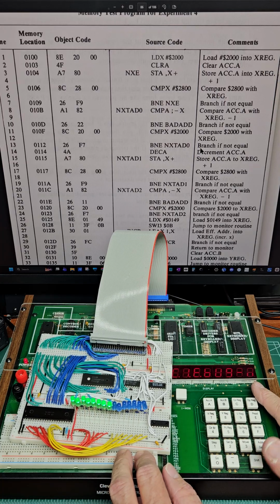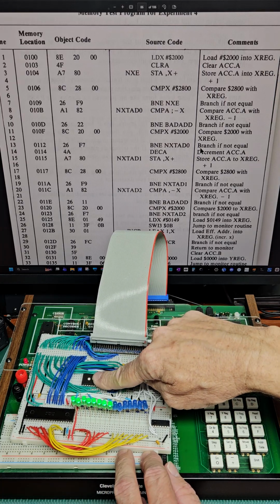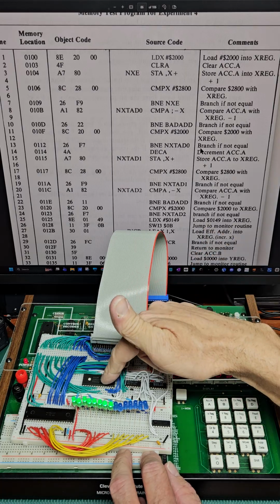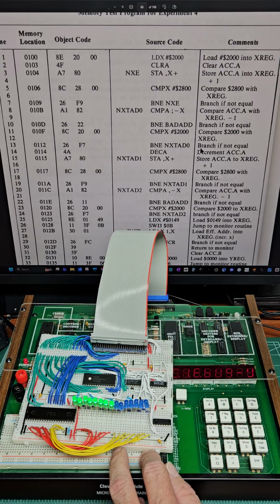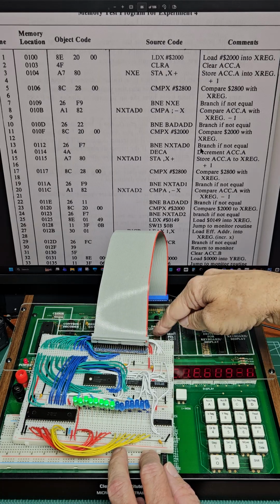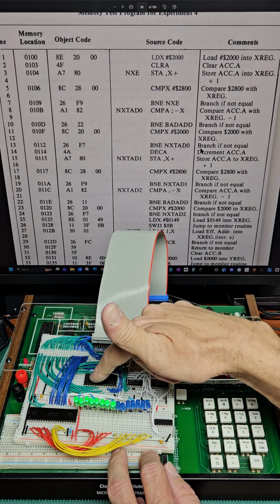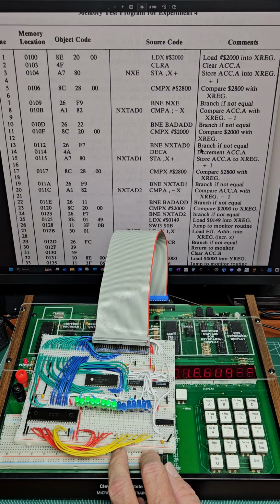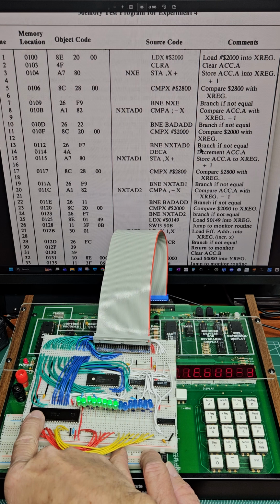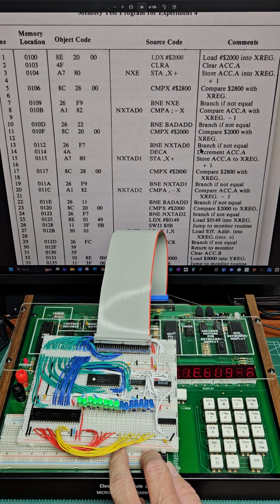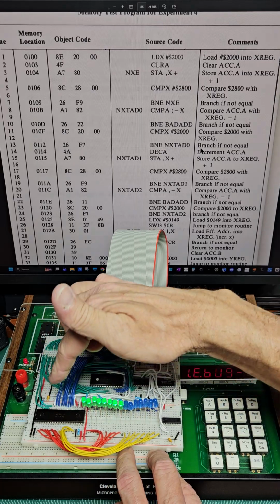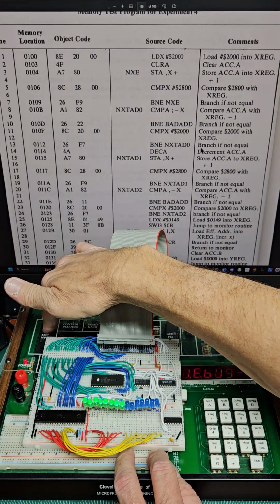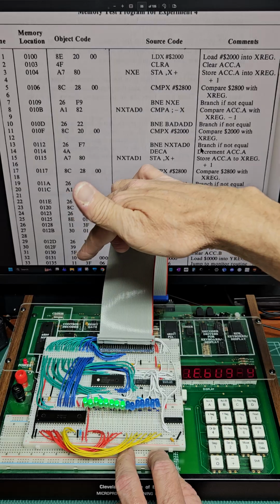And I wrote a program that I have on here onto the EEPROM. Now this is an 8K by 8 EEPROM, so it's actually 8 kilobytes of ROM. Actually, on the board itself, it only has 4K of RAM, so I've got a lot of ROM on there now compared to the RAM that's on the board. And then I also added on this another PIA, which is a peripheral interface adapter. So this is a 6821, which is actually created to work with the 6809 or 6800 series, I should say.